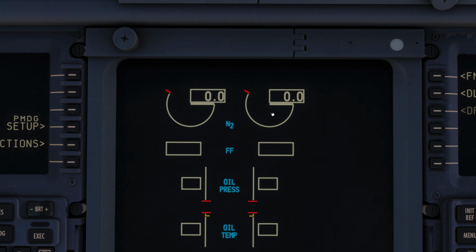N2 is usually going to rotate faster than N1 because of the higher pressures down there, and the N2 is basically an indication that we can use to monitor when things are going wrong inside our engine. During the engine start, however, it's exactly the opposite. During the engine start, N2 rotates first, and so we control when to insert fuel into the engine during the startup procedure.